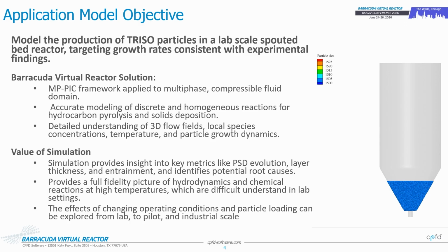The solution provided through Barracuda is applied with the MPPIC framework in a multiphase compressible fluid domain. We've also provided coupling of discrete and homogeneous reactions, and this would be for hydrocarbon pyrolysis, as well as the subsequent deposition onto the TRISO particles. Through this, you can gain a deep understanding of the 3D flow fields, local species concentrations, temperatures, and most notably the particle growth dynamics, as I was mentioning.